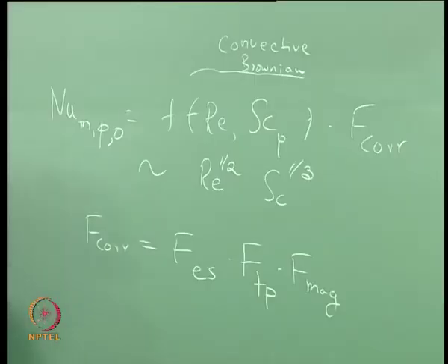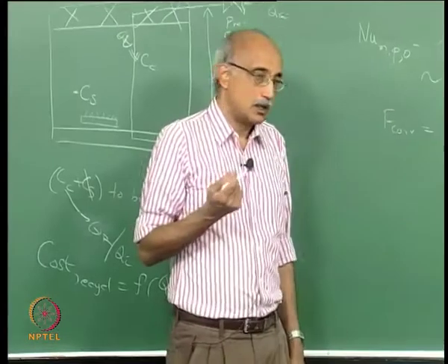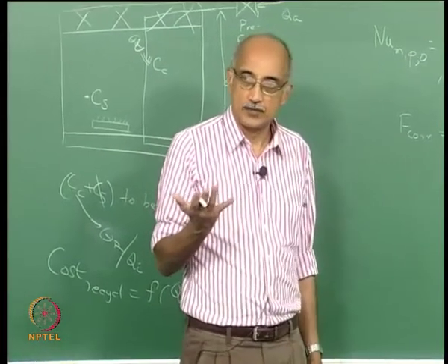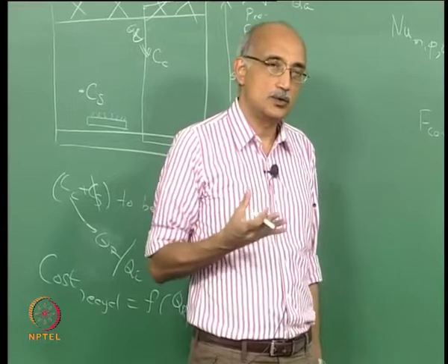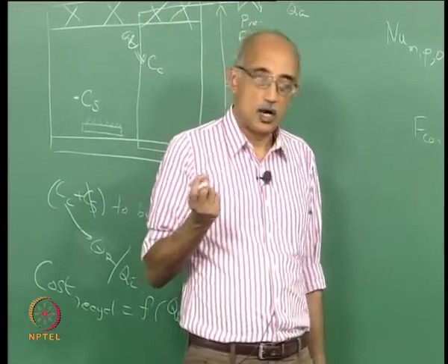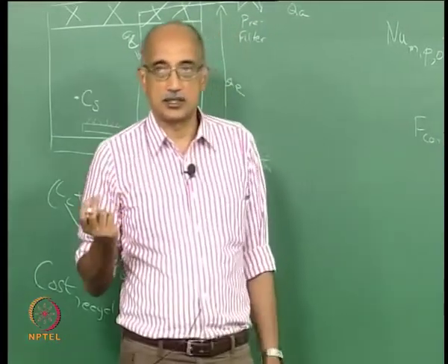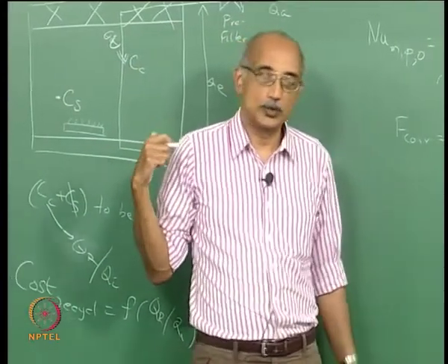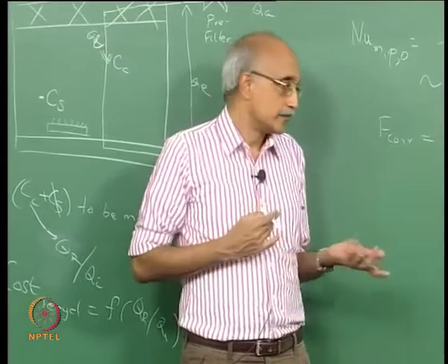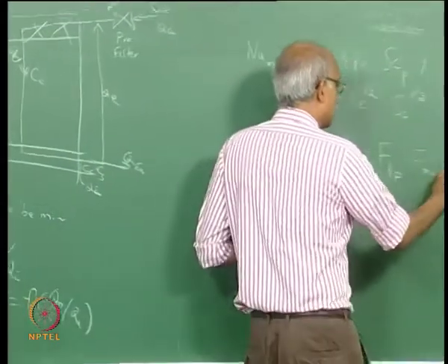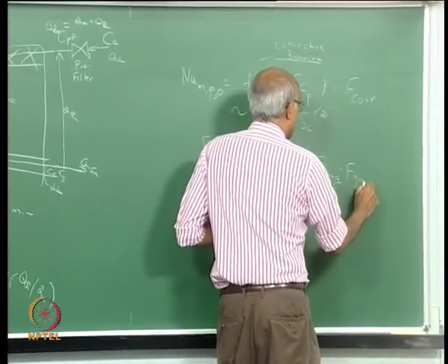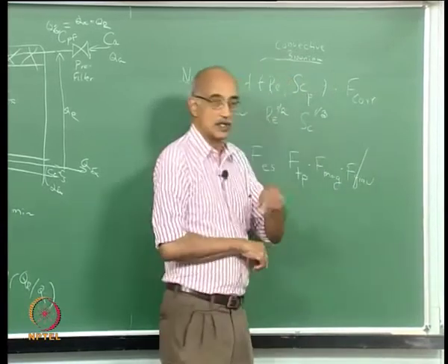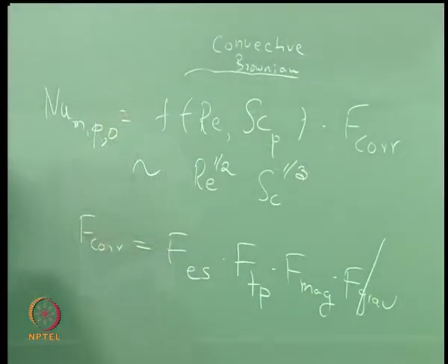The other type of flow that we have talked about earlier is gravitational, right. It's very unlikely in a clean room that you have large enough particles that gravitational settling or sedimentation becomes an issue, because these filters are very very effective in removing such large particles. So F gravitation is considered negligible inside most operational clean rooms.